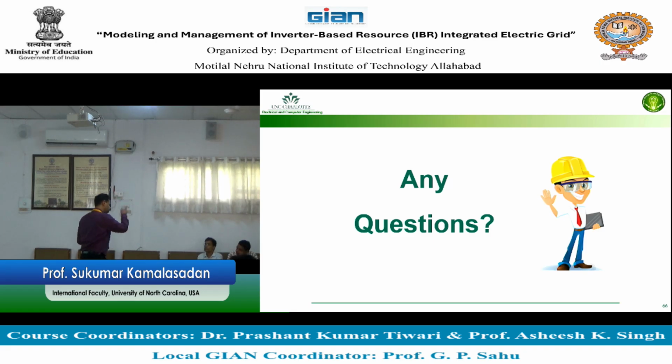You can also implement and see, suppose you have an inertia dependent source like a flywheel connected to it. What will happen to the power swings or power changes and then the frequency? So we can plot the frequency on the system also. So yes, it can be extended to other types of energy storage, frequency balancing or load balancing solutions. You can also implement on the same model to see what happens if you add a reactive power compensator like a STATCOM or some other devices.